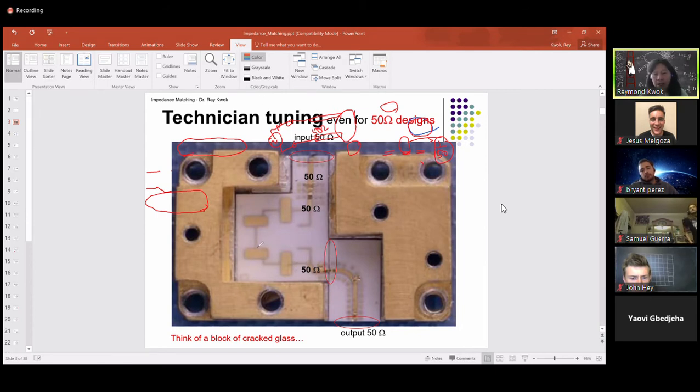Let's say the signal is going from here to here through a very thin line. A very thin line is very high impedance, right? To lay out a board, you can go to AWR and play with the tools: if the width of the line is narrow, your impedance goes up. So the impedance purely depends on the width of your transmission line. If you use a very wide piece of transmission line, that impedance is very low.